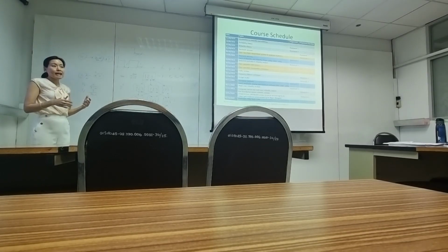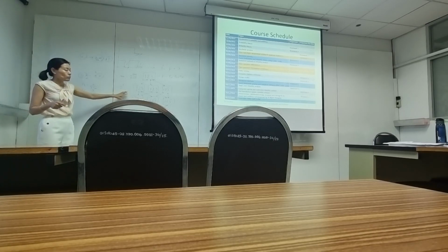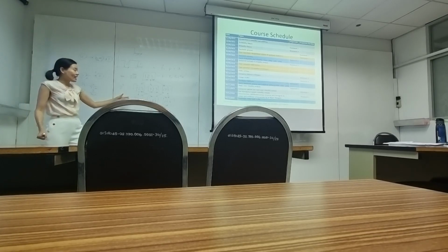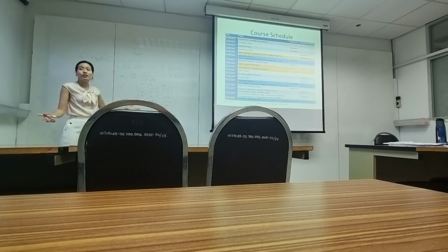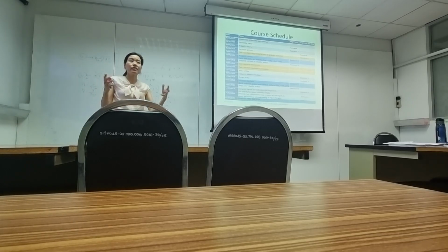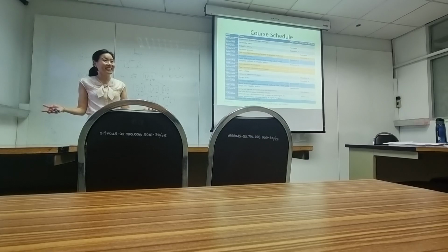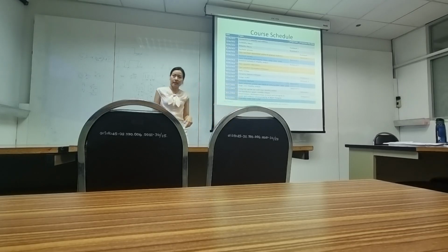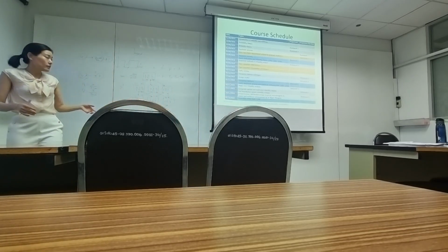So in reliability analysis, you don't only want to use analytical tools to solve it. Analytical tools means that you write equations and then solve the problem. You know the idea, right? You write an 8 by 8 matrix if you want the exact solution for this kind of state diagram, because it has 8 states. But for a big system, you have like a 1,000 by 1,000 matrix, and then you do the inversion. Well, what we do is use what are called simulation methods to solve the problem.